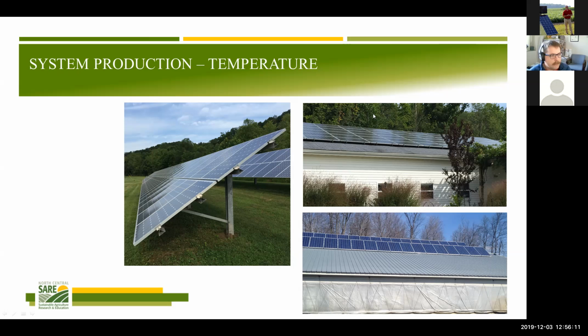Having it meet the same angle as the roof has a little better aesthetic than changing the angle. And the fact is that the solar panels are not a large piece of that cost of the system. They're a large piece, but they're not the largest cost of the system. So in some ways, if we need a little bit more production, it's almost easier to add panels than it is to add all this expense in racking to change that tilt angle.